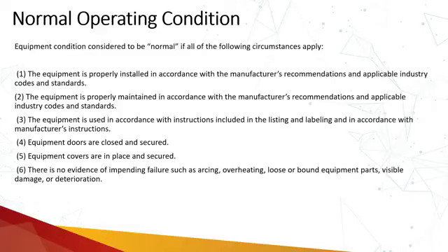For example, there may be a requirement that the equipment should not be operated under load condition. What is meant by load condition? There is switchgear which you cannot operate on load. First you have to remove the load, then you can switch it on and off.